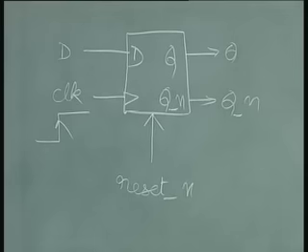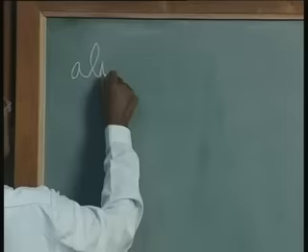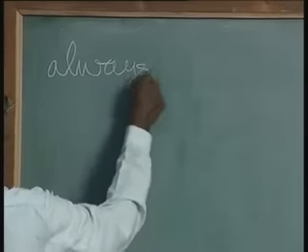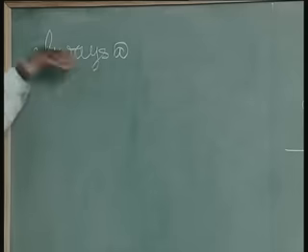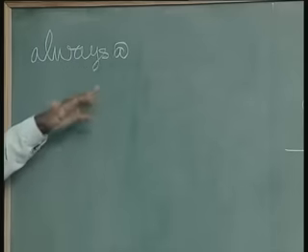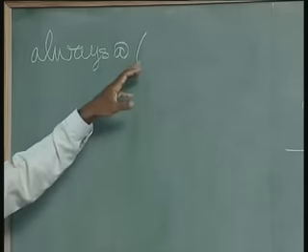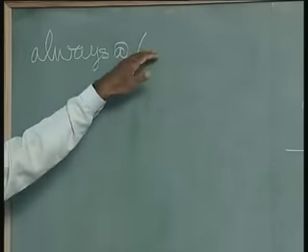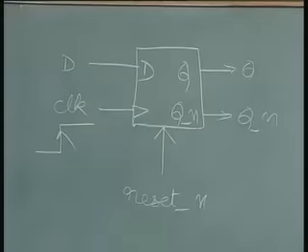What we will do first is reuse the same always block, but the connotation is different here, because this is a sequential circuit. We will use always at once again. This portion is common to combinational as well as sequential, but here is what makes the difference. Now within brackets the same inputs come into picture, but this time it is going to be a clock rather than the ordinary logic signals. So that makes the difference.